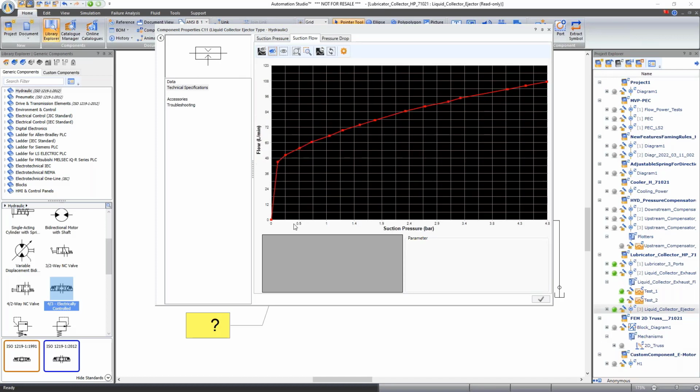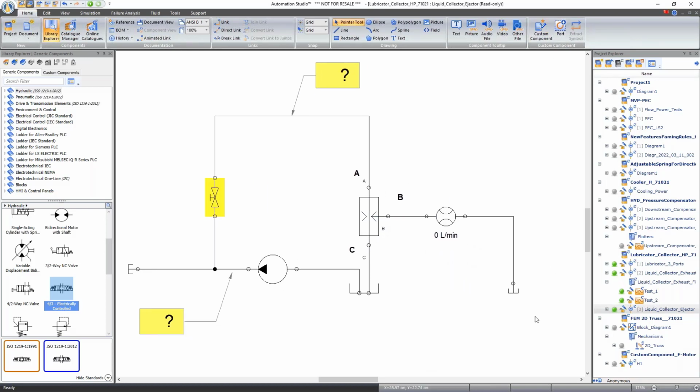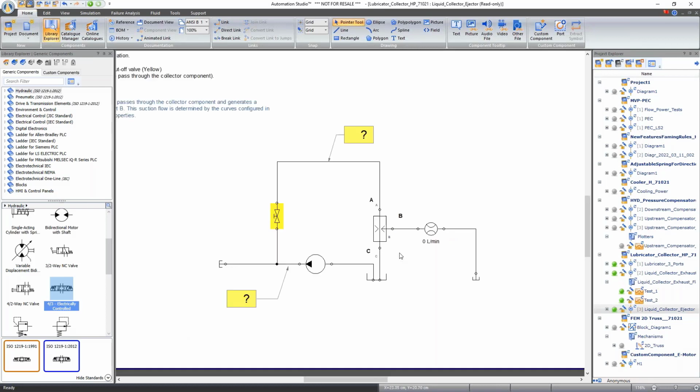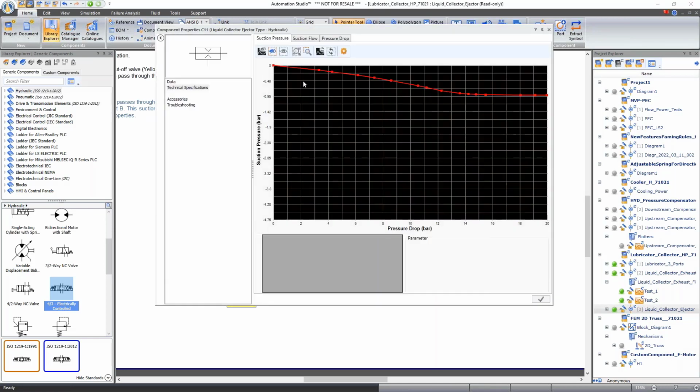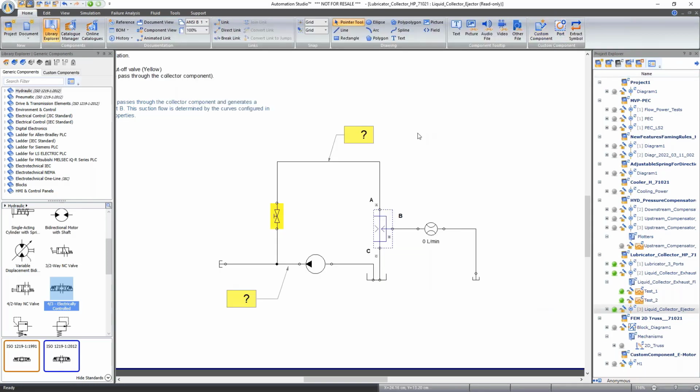And then based on the suction pressure generated, you will have a certain amount of effective flow in your system. Now obviously that depends to a certain extent on what the circuit is here. If you have a reservoir directly connected in, you will never be able to generate enough negative pressure. So it's sort of an ideal circumstance. It depends obviously on your system, but this is the behavior that it's designed for. This is something you will take from a manufacturer specification for that component.